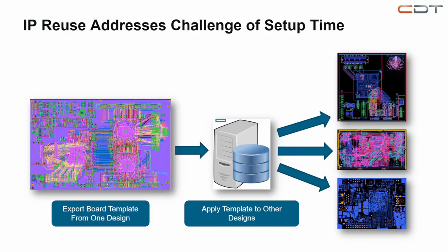The other large challenge that we deal with in constraint management is just the volume. Working on large designs that have thousands and thousands of nets is tremendous work. It takes a lot of time to set up the constraints for all of those nets with intention. And I say with intention because Constraint Manager is a spreadsheet-based tool.